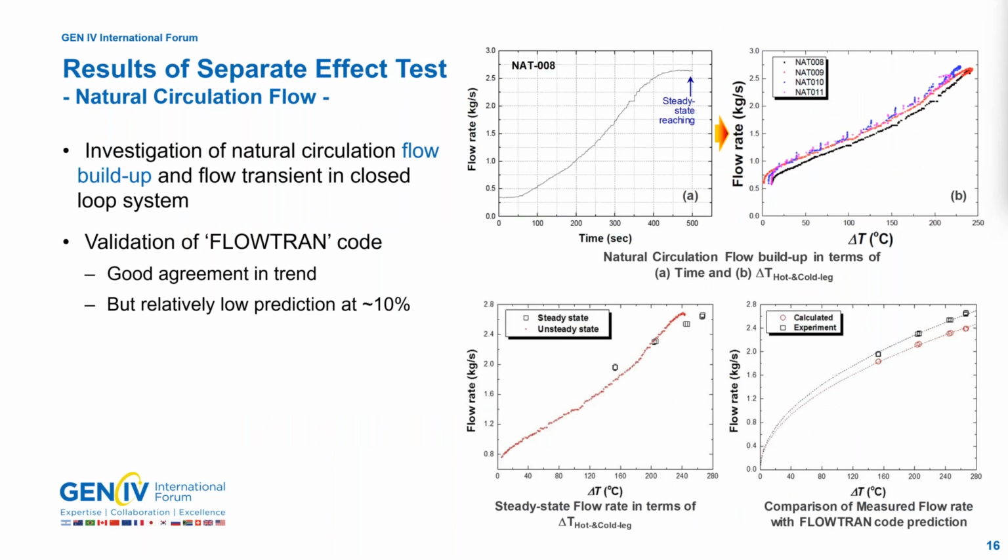And lastly, with Stella 1, we were able to test the natural circulation flow development. Because it is a 3-loop system, we can set the condition for natural circulation to occur in the sodium loop. So there is one sodium loop for heater and DHX shell side, and there is another sodium loop for DHX tube side and AHX tube side, and there is one air loop for AHX shell side. That makes 3 loops: 2 closed loops and 1 open loop.